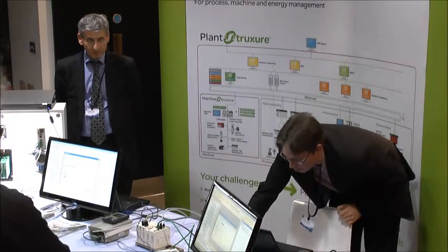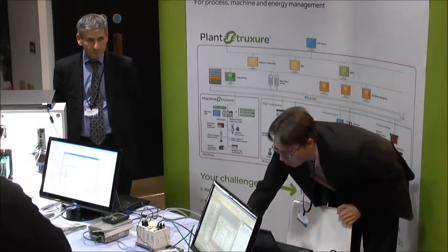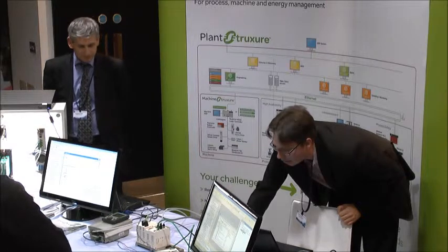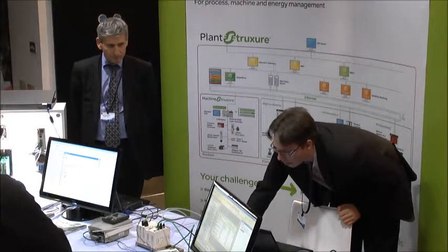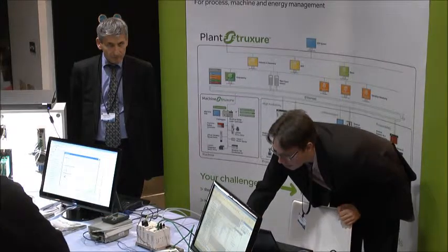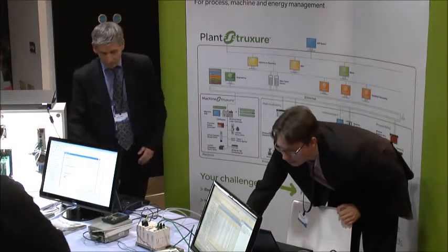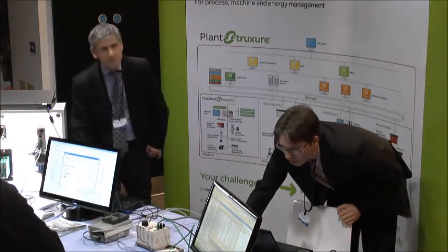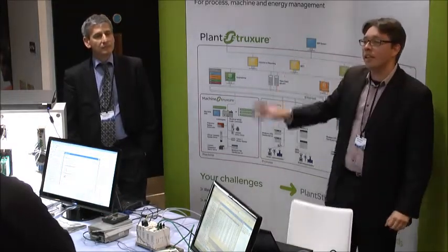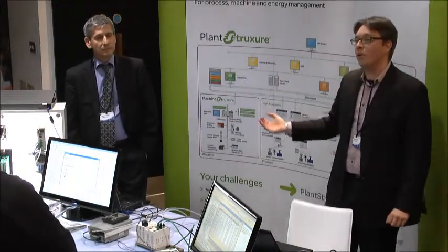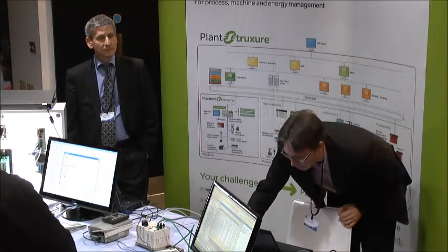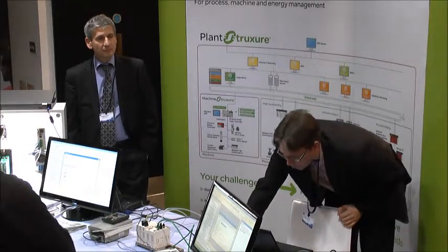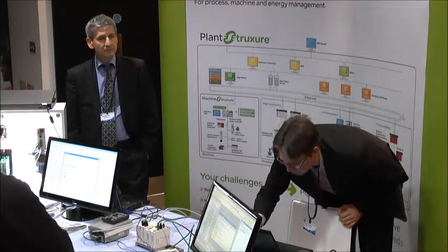I select it and give the name to have automatically the good variables. In my frame application, I can see the Profibus Remote Master. If I click on Add, I have the list of all DTMs installed on my computer and compatible with Profibus DP communication. I select the first one, change the name or not,